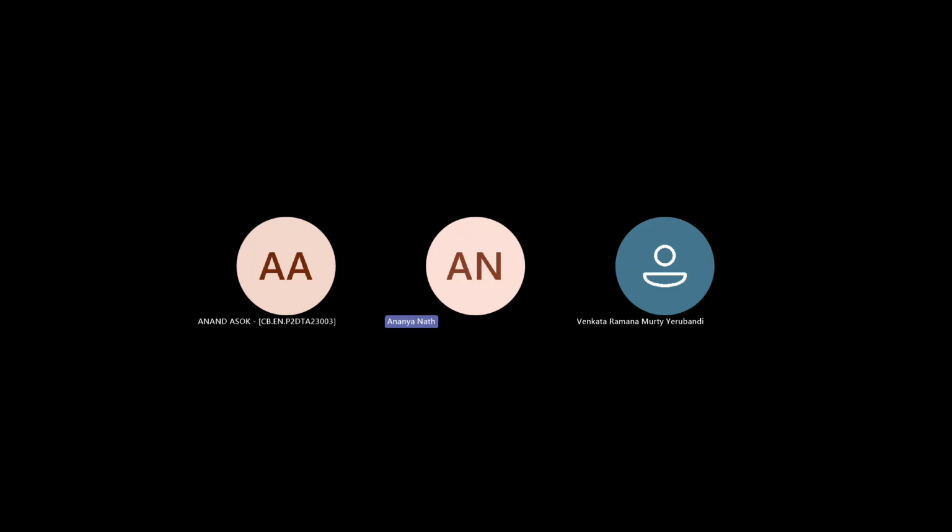I am still using STL only. I am converting it to STL, and a lot of repair work will be there. We are finding some gaps, and correcting the STL is quite difficult. You have to have large computational power in your system, and you have to have other software also.